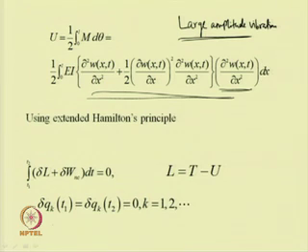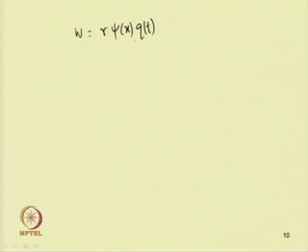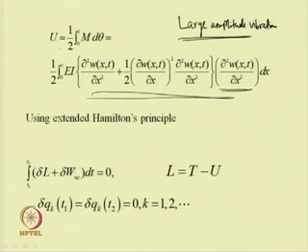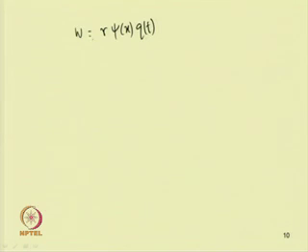Either one can apply the Galerkin principle, or one can apply this equation, that is W equal to R psi x q t, in the kinetic and potential energy expressions and then apply the Hamilton principle, or after applying the Hamilton principle and getting the differential equation, one can apply this equation there to find the temporal equation. So, both methods will yield the same equation.